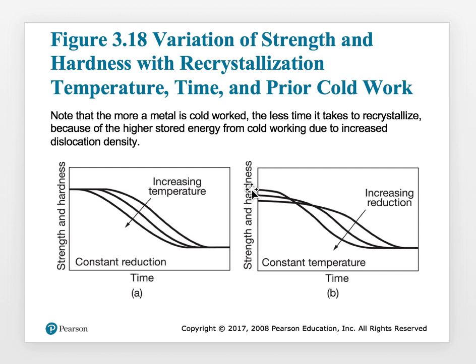Because when you have increased the amount of cold rolling, you have increased the amount of energy that you have put into this material. And that energy is sufficient to decrease the strength after the heat treatment.